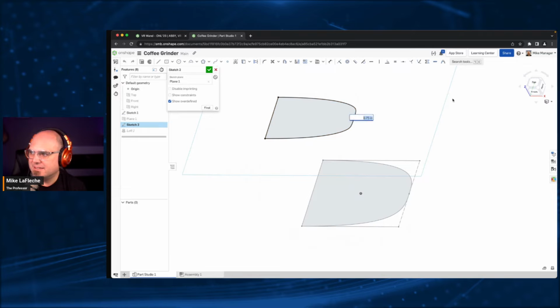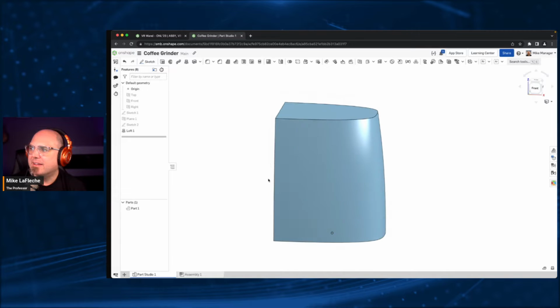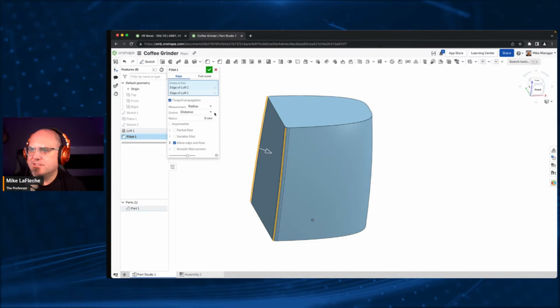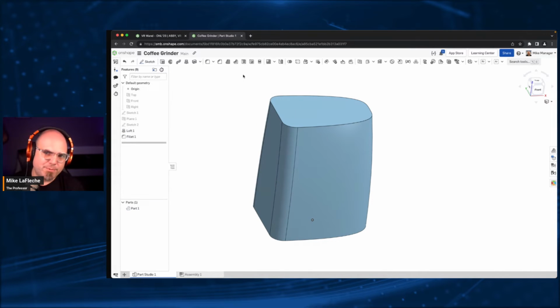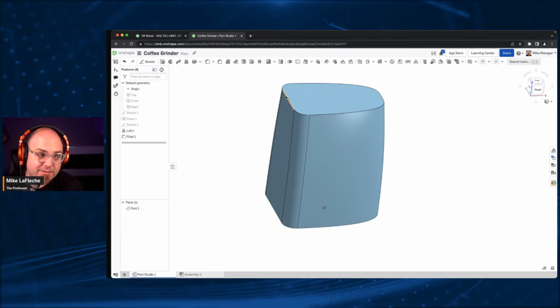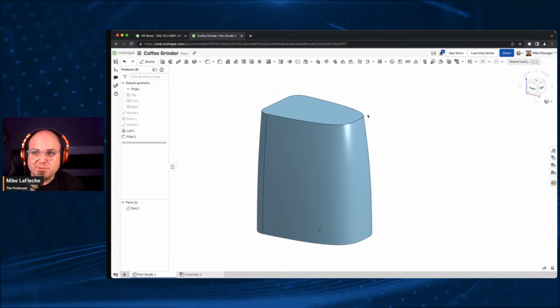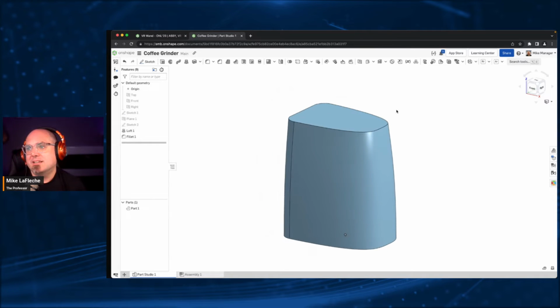So that's a little bit weird. I'm going to call that 10 millimeters. I like the way that looks better. All right. And I'll drop in a couple fillet radii. I'll just do a window select and I can tell it to be 15 millimeters. So pretty typical at this point, right? Nothing mind blowing except that you haven't had to install anything and you haven't needed any sort of license, you just sign in essentially, right? It's much easier than a traditional system.